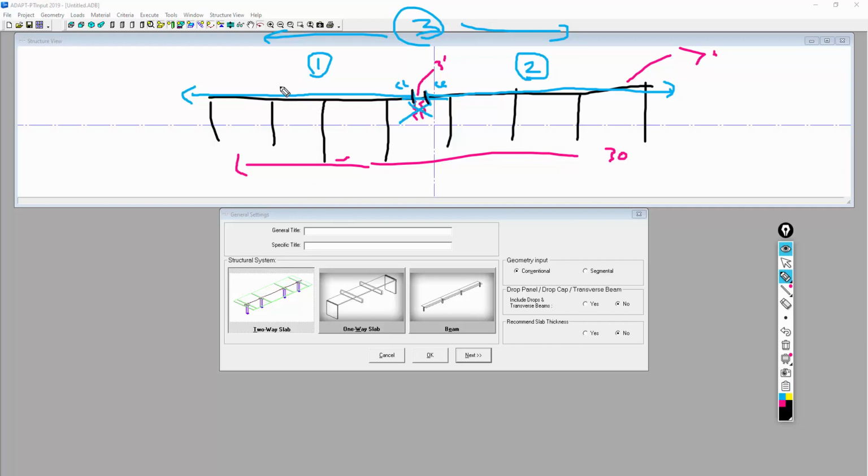We have basically 3 tendon types in this program. There's tendon A, there's tendon B, and there's tendon C. All 3 of these tendons can be classified using different shapes per span, so that we might have a reverse parabola, a straight shape, a partial parabola, or a simple parabola if we zero out the inflection points. So these allow the user to enter different shapes. One of the restrictions, however, is that tendon A, I'll go ahead and put a square around tendon A, has to be modeled end to end.